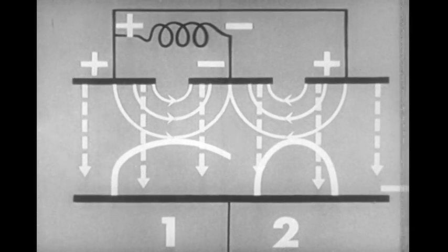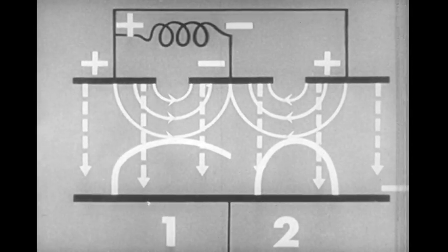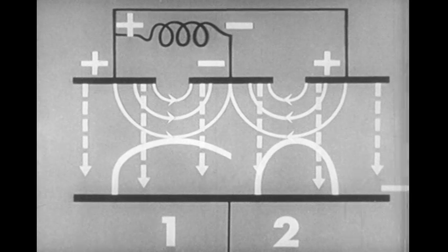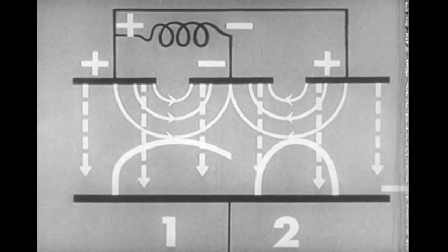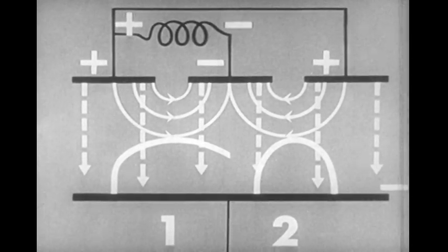The net result is that more energy is given to the RF field by the electron in region 1 than is taken away from the field by the electron in region 2. In this way, tube losses are overcome and oscillation can be maintained.